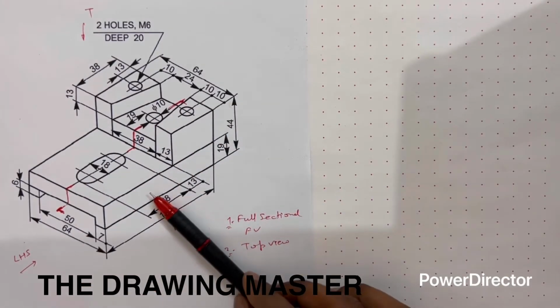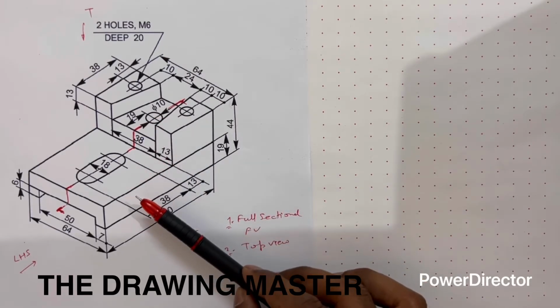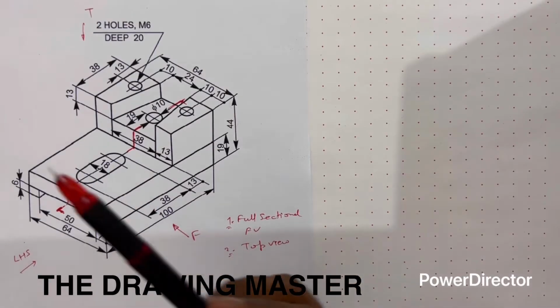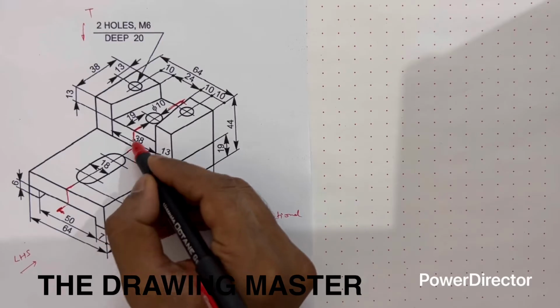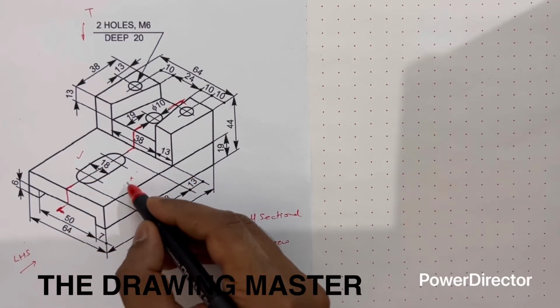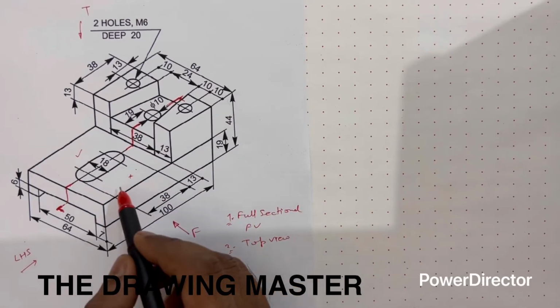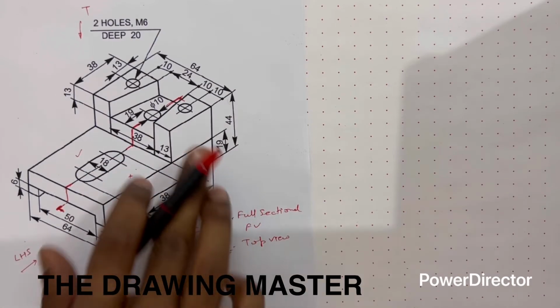Now this is the front view, but if you cut this object, it will be the full sectional front view from this direction. So basically for the full sectional front view, we are cutting this object through this path. This portion will be removed and we keep this portion. It's an imaginary cutting plane, right? In actual, the object will remain there. We assume that we have removed this part, 50%.